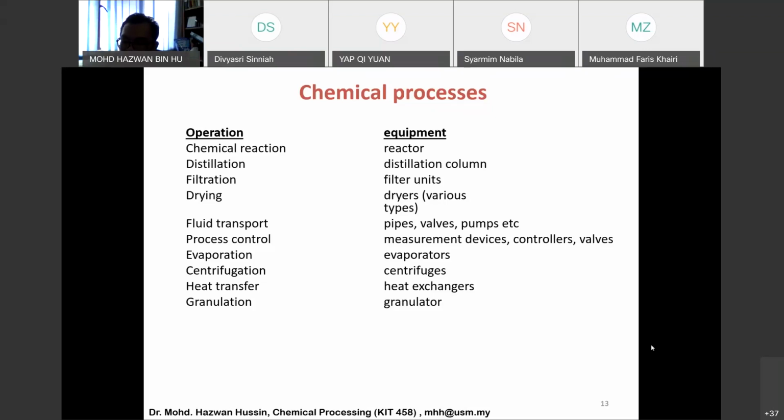So in industry, actually, they use solid minerals to filter solid particles, for example celite. Celite is actually calcite, like a calcium carbonate material. Sometimes they also use silica powder. What they do is they just pack this into a container or something like that, and then it will function as a filtering unit.